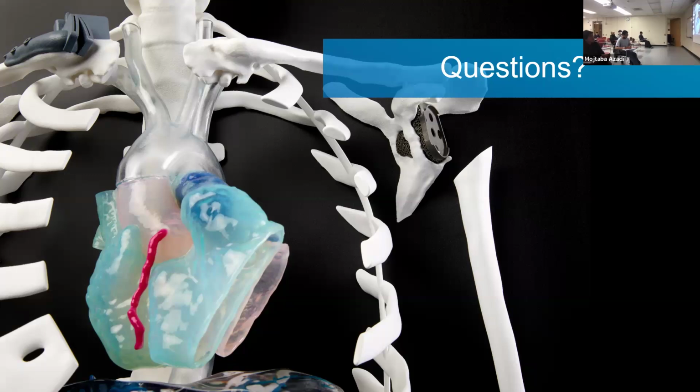Oh, sorry, one last thing. I initially did the isolation of the lumen geometry with 3D Slicer, which was not as detailed. Once it exported, there were a lot of cutoffs. When I isolated it through 3D Slicer there weren't any gaps, but when I exported it, there were these huge gaps. That could be because of the number of faces or facets; they were fewer when I saved them than what it looked like when I was making it.